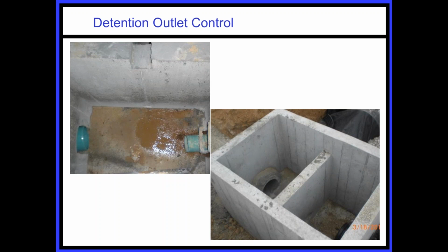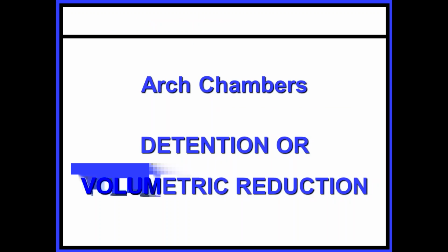It may just be a very small pipe at the outlet. But with that particular condition, if you have one of those high intensity, short duration events with a high runoff, you might exceed the capacity of that outlet pipe, and then you would have significant ponding upstream from even the detention, which certainly isn't desirable.